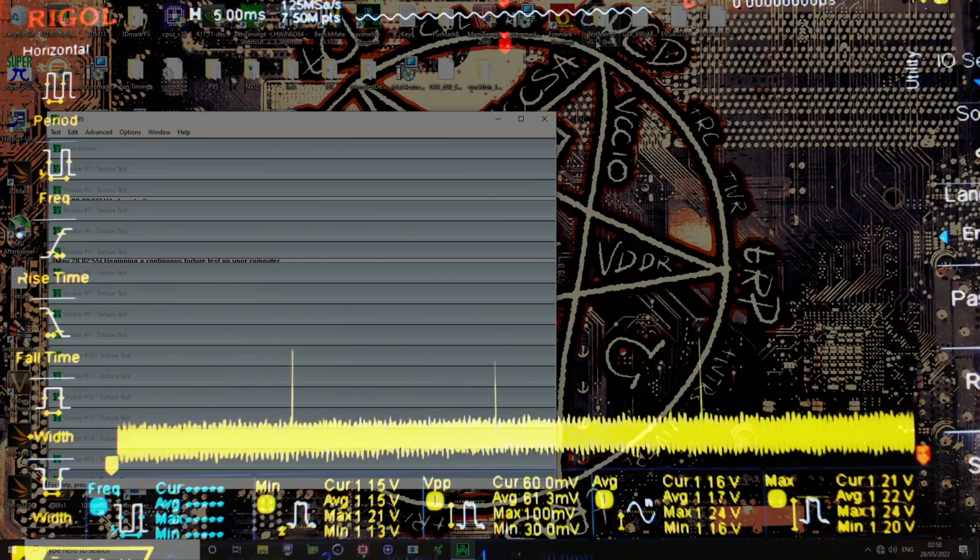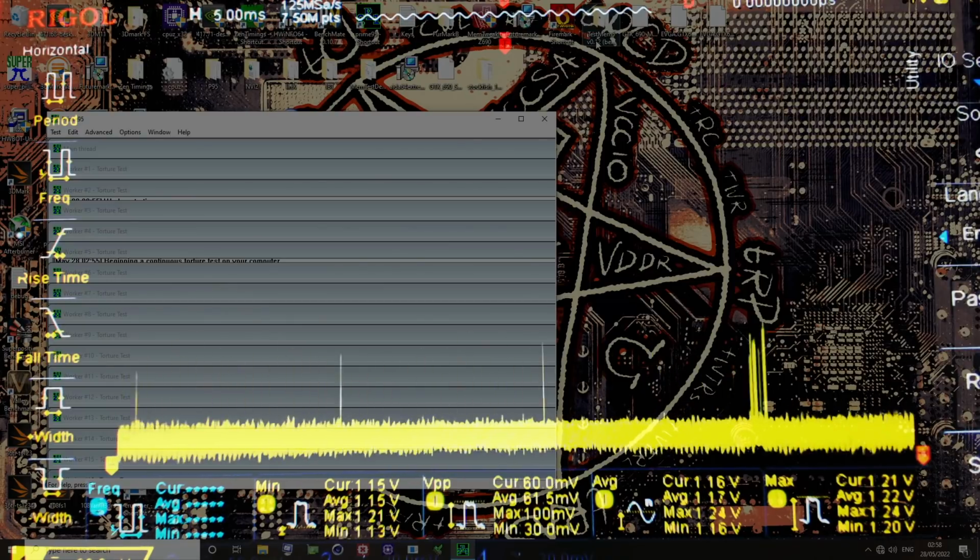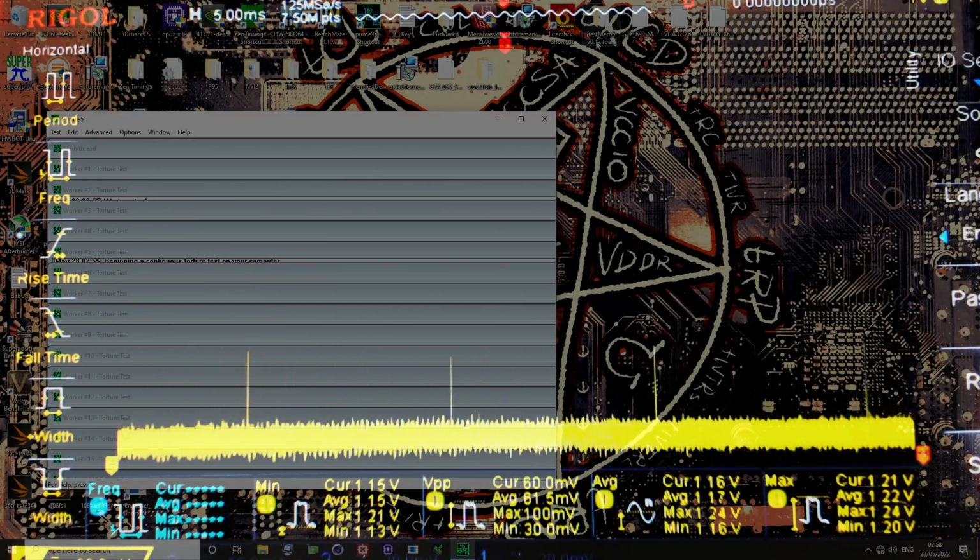If this is actually just connecting the Super I/O in parallel to the Vdd sense circuitry, in parallel with the voltage controller, then that would certainly explain why the voltage regulation changes drastically based on what sense setting you're using. I'd hope it's not picking up any noise from going to the Super I/O.